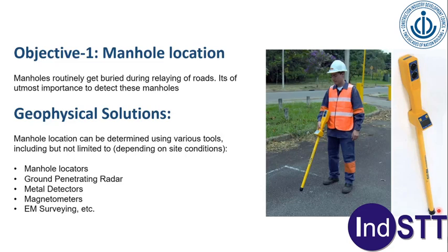GPR again comes in very handy for manhole location, as do metal detectors, magnetometers, EM surveying, etc. So there are different tools available for finding the location of your manholes which are otherwise not visible, buried under the layer of road, etc.